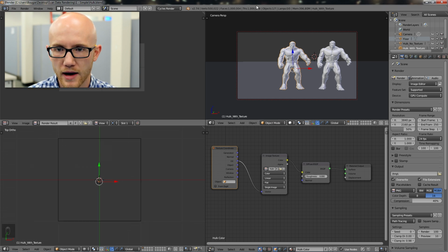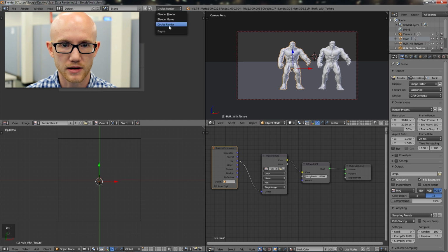All right, so here we have the general Blender screen. This is not what it's going to look like when you first install it. It will only look like this if you open the projects that I've included. So if I come here, a couple things that you want to set up. You can open my project, and you'll want to check to make sure you are using the Cycles render here at the top. It comes default using the Blender render.